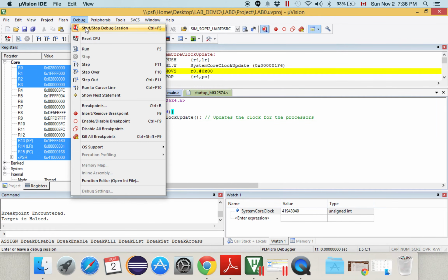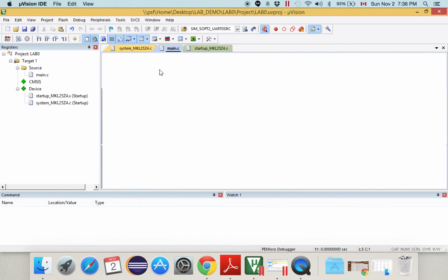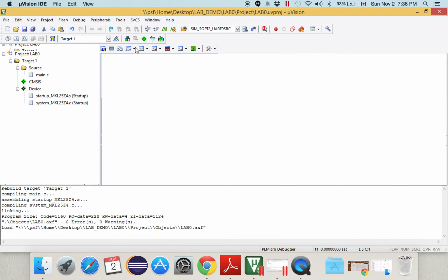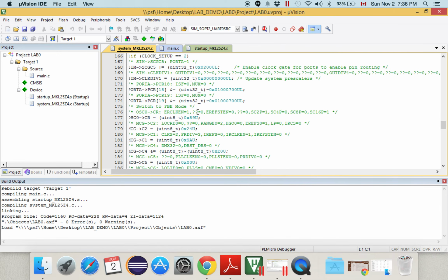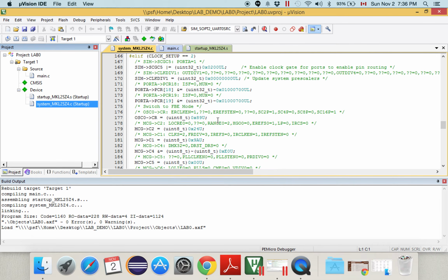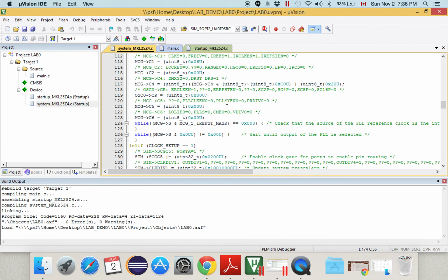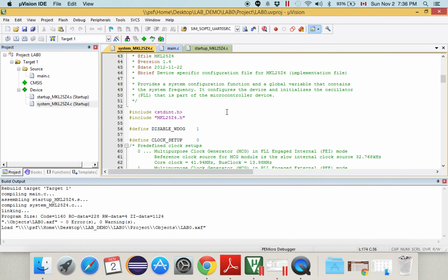The really important thing in this startup code is that you need to select the correct configuration for the clock. So now let me explain the problem. We saw that the clock is locked at 42 megahertz, but we need 48 megahertz for reasons which you will face later in your design. So it's good to select 48 megahertz as our core clock.